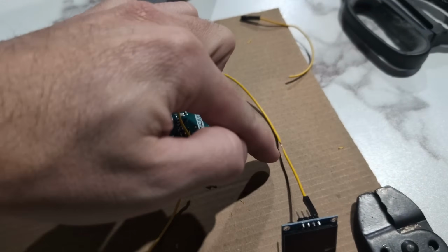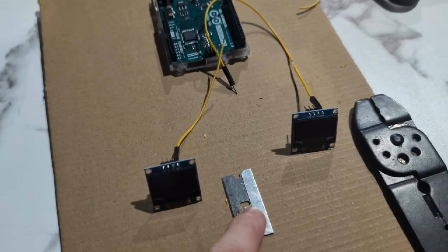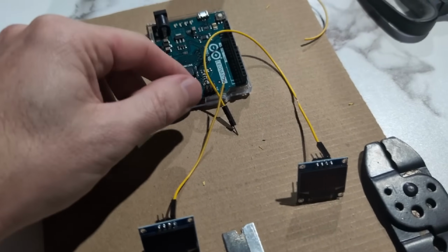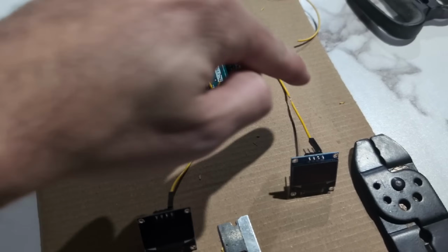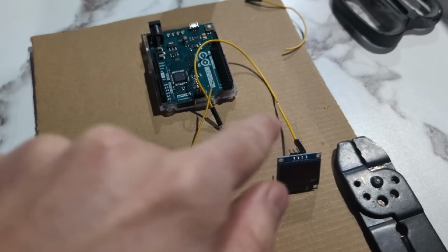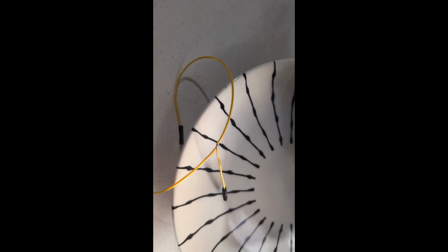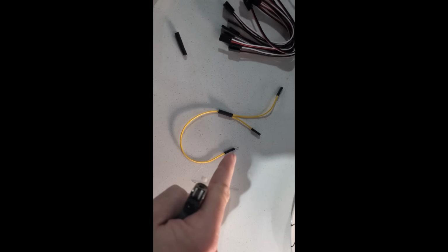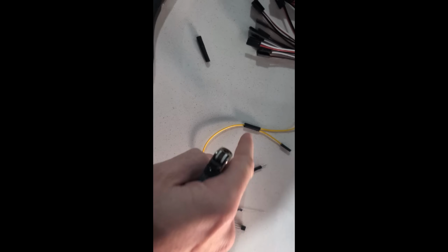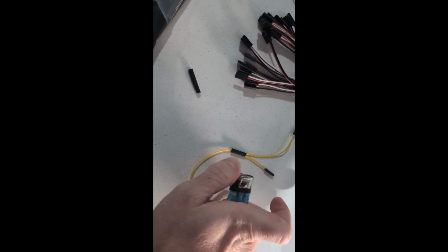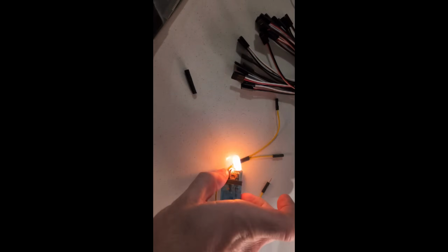Because the wire is really thin, what I decided to do is use a razor blade to strip that back. And then I've just cut this one here and I'm going to solder that to there and use some heat shrink to go over it. I've wrapped the wire around that area and now we're ready to solder. I'll push the heat shrink over there. I cut it a little bit because it was too long. And then just pushed it over these two just a little bit. And now I'm going to use a lighter to light this up and then shrink the heat shrink.